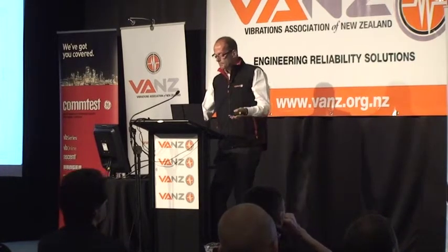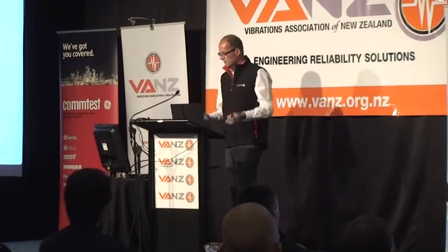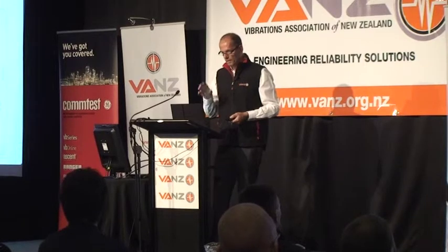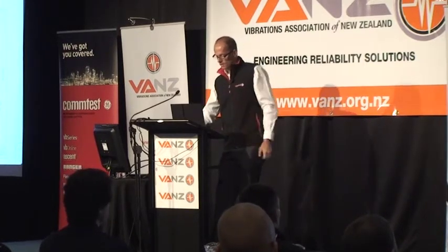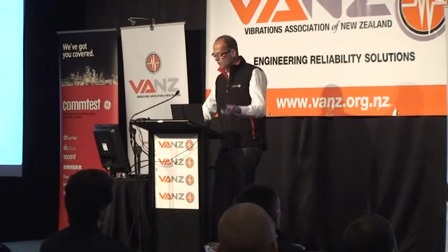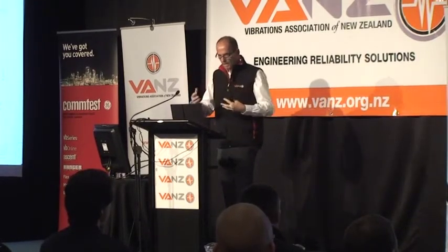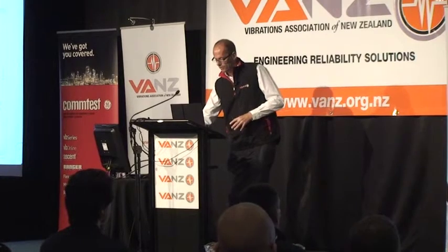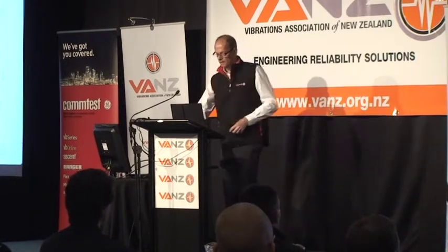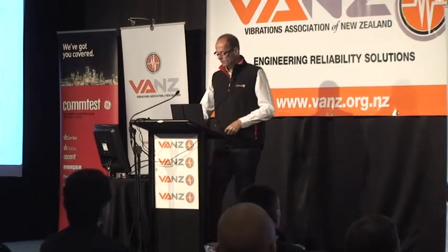If there was misalignment, well, it depends on the type of misalignment and all of that, and I'll mention a bit more in a second, but we'll see a change in that vibration. Rotating looseness, we get lots of peaks called harmonics. And because of the impacting, the bottom of the graph, the noise floor, can lift up. And these are all telltale signs that we can look for.